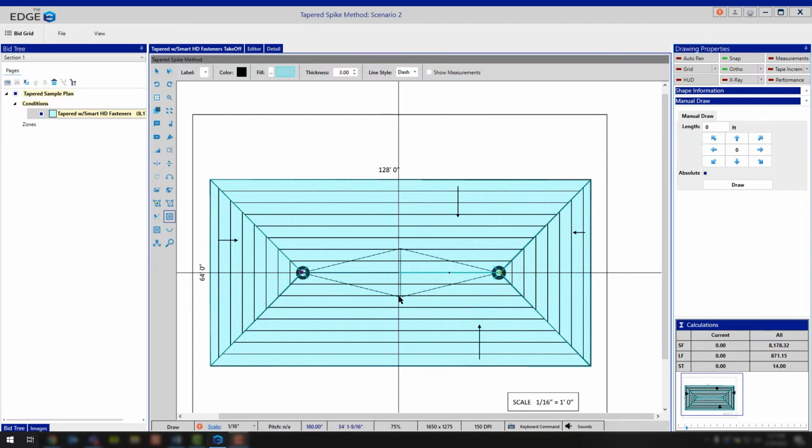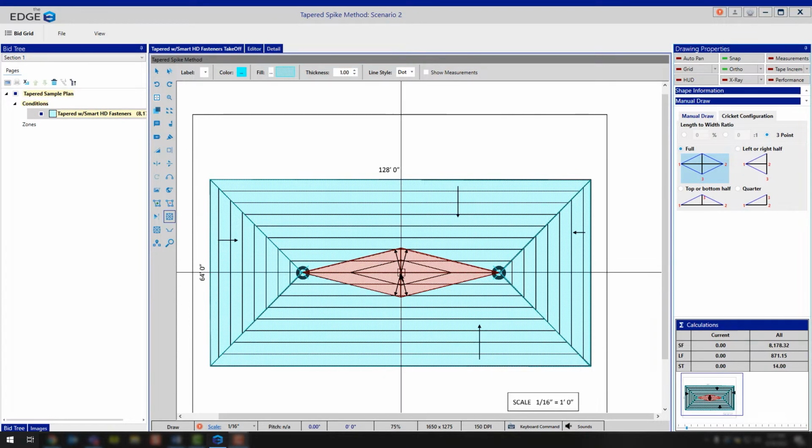Now one thing that's unique is if you are in ortho, it is going to make you snap to your point. So instead of toggling off ortho, you can simply just move your line down to where your crosshairs match up with your drawing and left click, so that way you don't have to turn the ortho off to be able to get your line to the right spot.